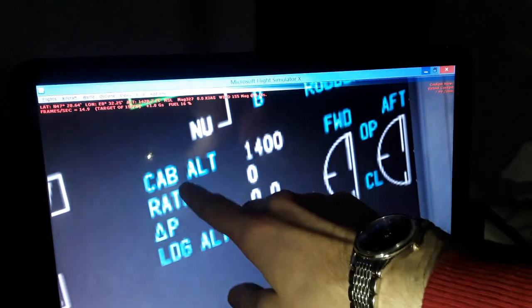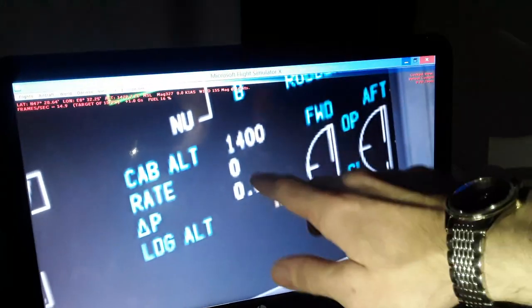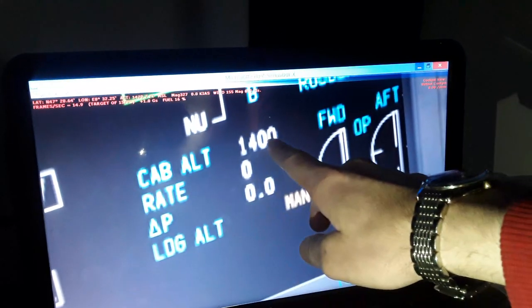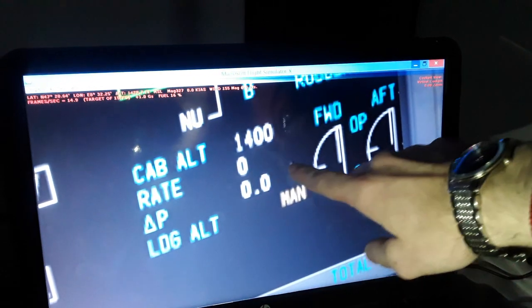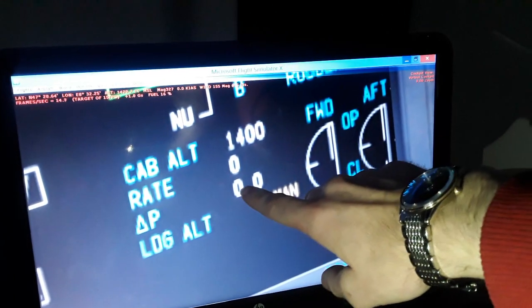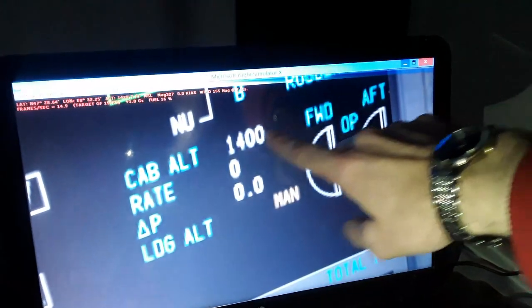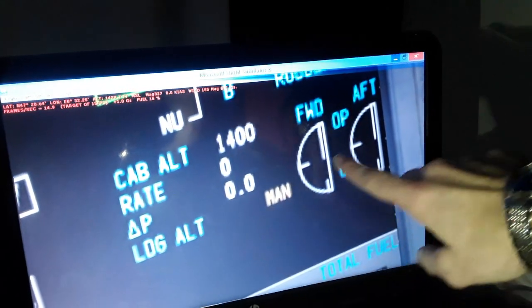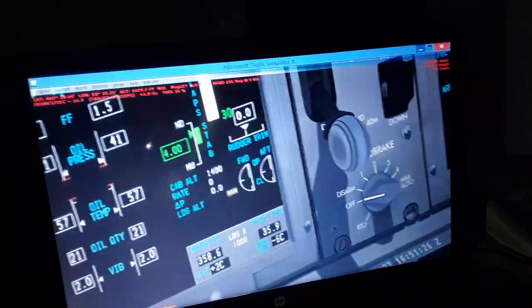So you can see when we fly, we pressurize or depressurize the cabin, climbing or descending. We have a differential rate, it can go 7.8 psi maximum pressurization when we are at 43,000 feet, and cabin altitude 8,000 feet, landing altitude also, and the outflow valves position over the climb.